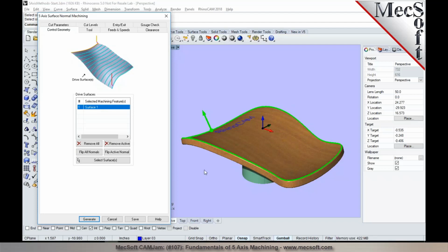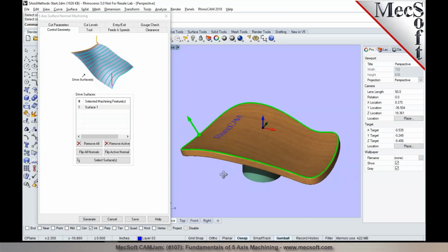Well, I think what we really do internally is we take that tool normal or the surface normal at every point along that tool trajectory from the drive surface. But then later on, the toolpath could be modified using either lead, lag, or tilt angles. So it's not necessary that it's always normal to the surface. But the initial starting point for us for calculations is the surface normal.